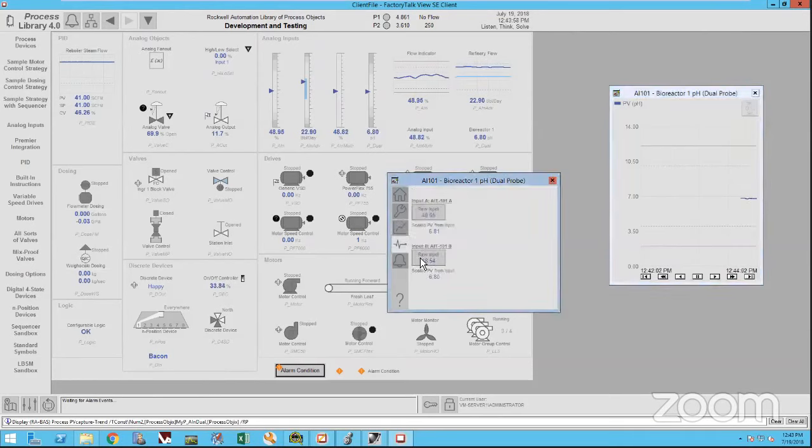And then all of the alarms are built into this. The diagnostics are also built in. So you can see what your raw input coming in. This is something different than the older library. You couldn't see that in the past. You can only see the scale values after the fact. And all your alarms that are pre-built. So this is an analog input, so you can define which one of these you care about. So if your system doesn't have a low, low, high, high, or you don't have a low and a high, just ignore them. You can disable everything at runtime.